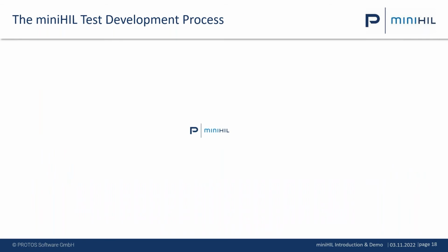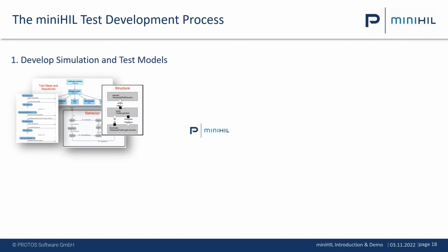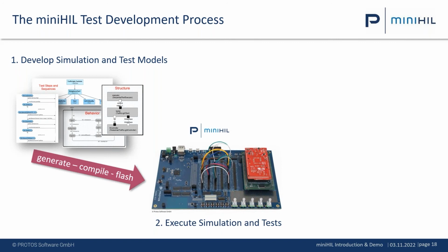So if you want to simulate and run test cases, you also need to develop the simulation and the test cases. Therefore, we do have a model-based development environment. It's a component-based approach based on the language ROOM, real-time object-oriented modeling. You model the structure and the behavior of the environment simulation and of the test system, also the test cases, and from there you generate the code as C code.